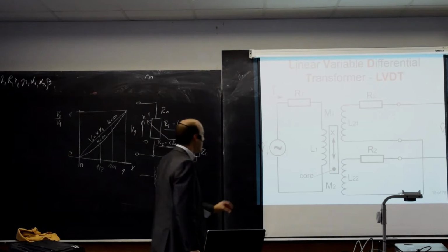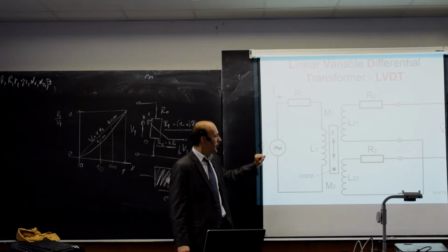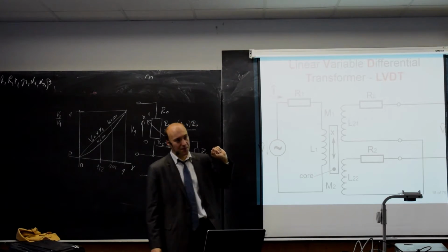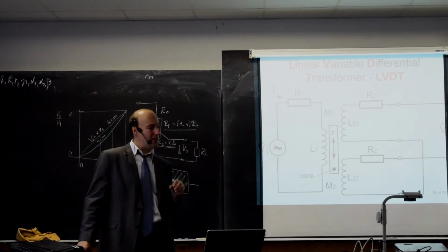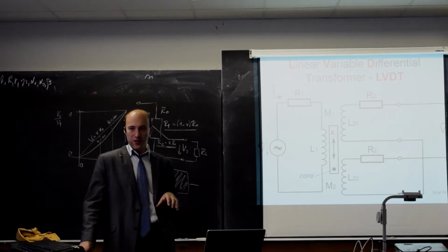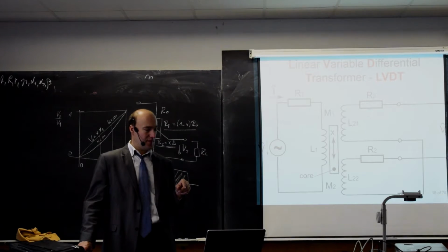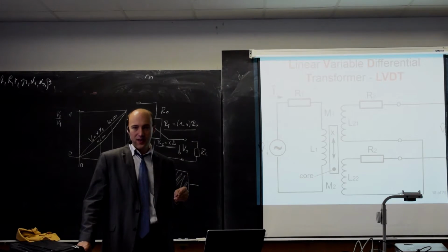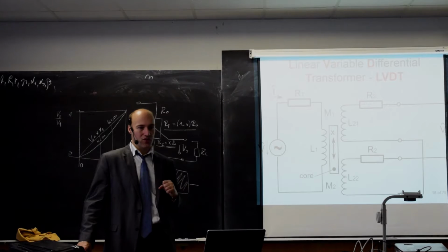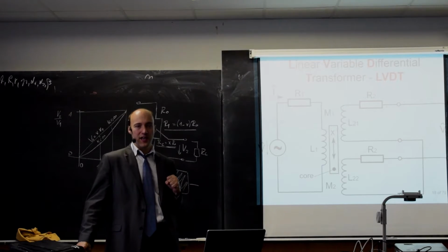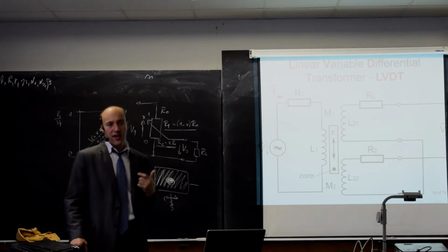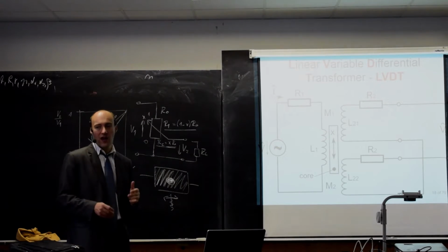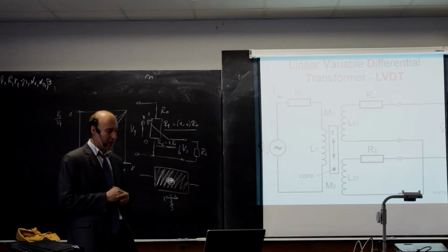So here you will need an AC power supply, and the AC power supply is in some cases built into the sensor. So the sensor is powered by DC, but there is an integrated electronic circuit that creates AC voltage from it, powers the electronics, and then eventually converts this to a current or output signal.